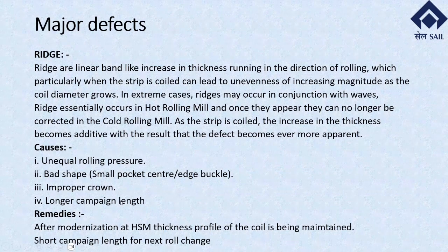Then, when crown is not maintained, and also when HSM produces coils for a longer campaign length between two roll changes, this can also account for ridge. As for the remedial actions taken after modernization, HSM has tried to maintain the profile of the coil.